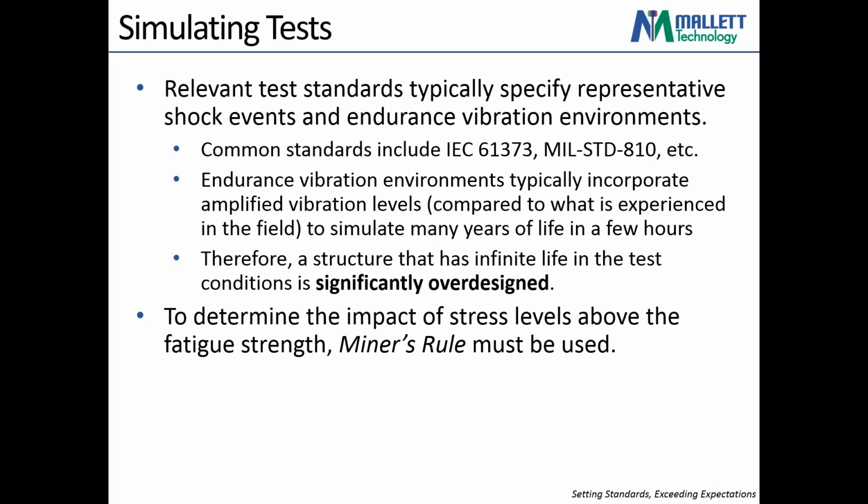The caveat here is we most often see this at Mallett when we're simulating test conditions. Typically, test conditions are meant to represent, let's say, 20 years of life in a 5-hour time span. So you have vibration levels that are significantly higher than would actually occur in operation.